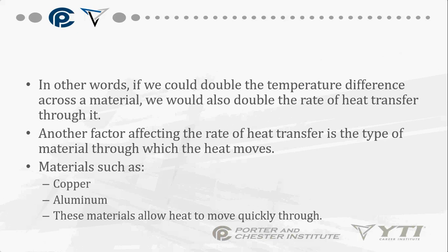So if you look at a baseboard and you see that all the aluminum fins are kind of crushed or meshed together, what do you think that's doing with the heat transfer ability of that baseboard? Is it raising it or lowering it? It's reducing it. It's losing surface area, so you're getting worse transfer. Right, you are losing it.